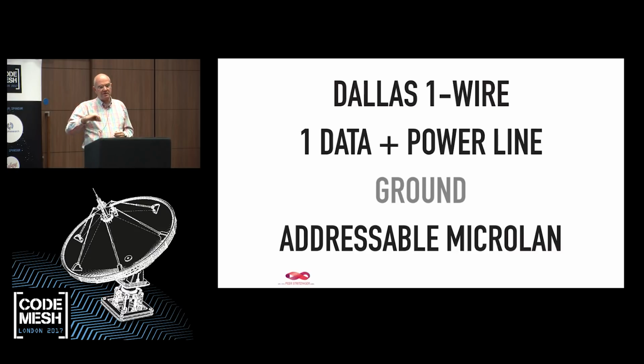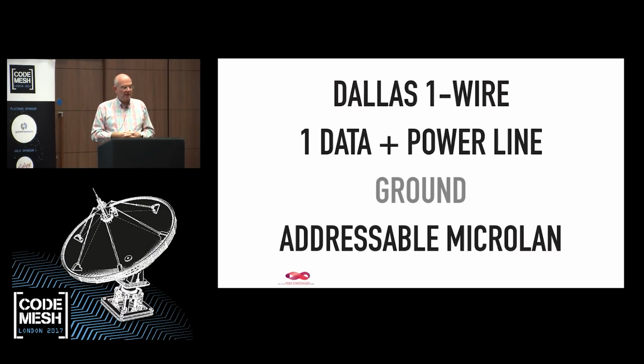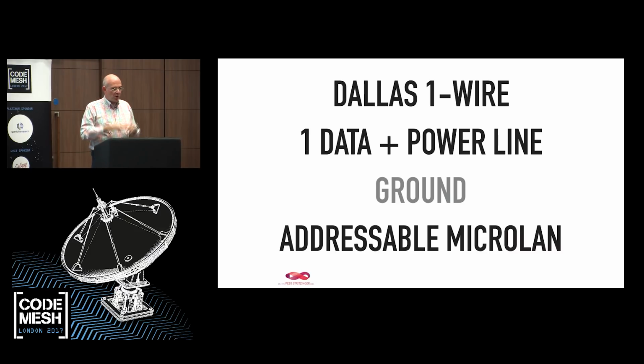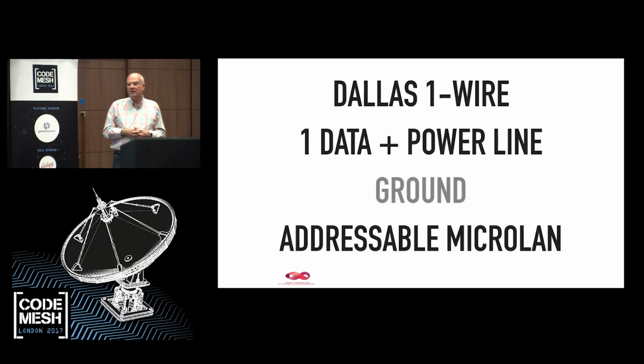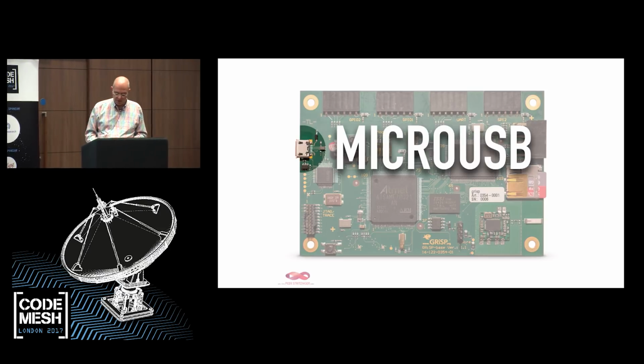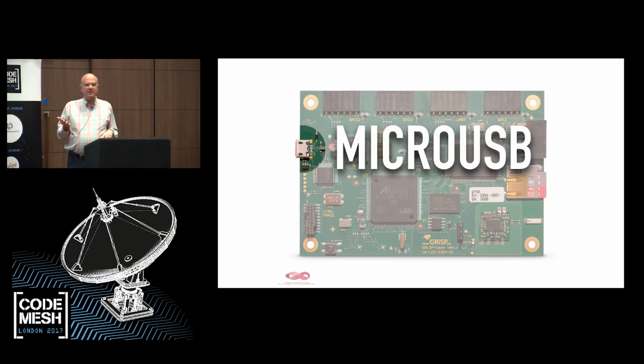And the sensors, which was the actual new technology back then, have a 64-bit unique ID burned into the sensor. So you always know every sensor is different. And what you normally do, you hook them one by one and then see who shows up, because you can search for new IDs. Who shows up here? And then you can actually say, this is topmost, lowermost. There are all kinds of things. You can get sensors for this.